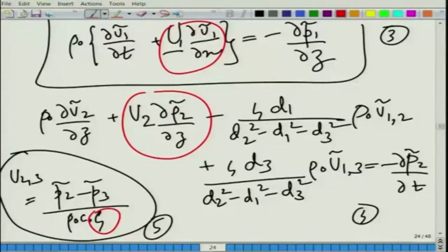We still assume our small segments do not vary much, and we can analyze a special muffler configuration called a CCTR, conical concentric tube resonator, where the outside cavity is of conical shape. Then we can use this matrizant approach in its full form, completely harnessing the power of this nice mathematical approach.